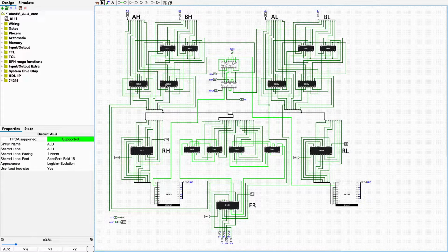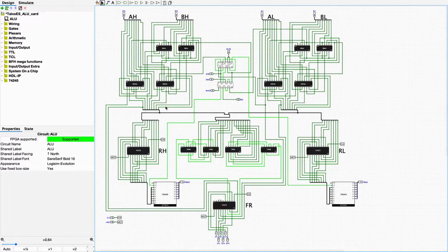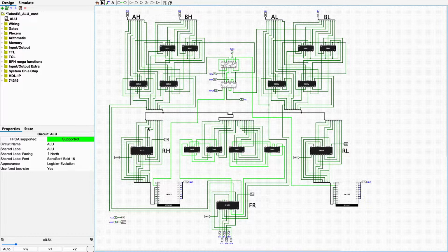So you have to write the results of the ALU computations into dedicated registers, not the registers of the general purpose register file. They have to be written into local registers here, so you don't interfere with the value of the operands that you were reading during that one cycle you have to perform the computation. That's the only reason.